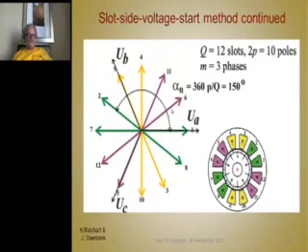And remember, we've color-coded here phase A, phase B, and phase C. So you color-code them here. So now from this slot numbering, you could pick where all the coils go and develop your winding chart by calculating this angle, which is a relationship between the number of poles and the number of slots to determine where all the coils go. That's a neat system.